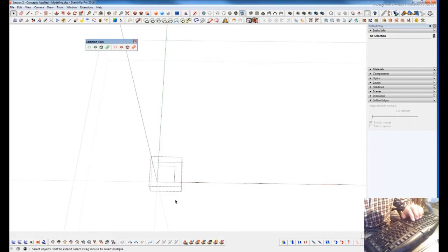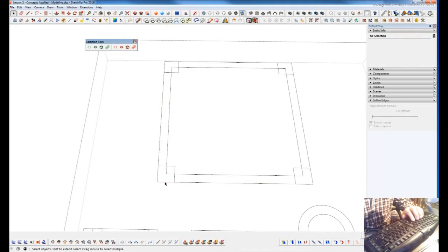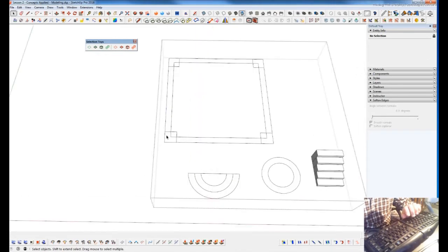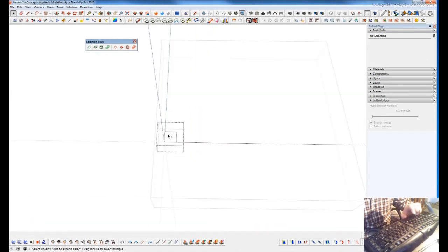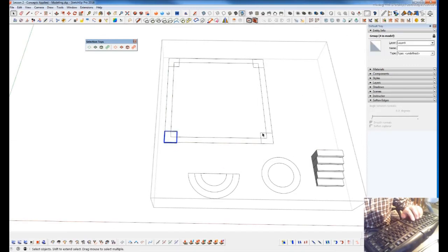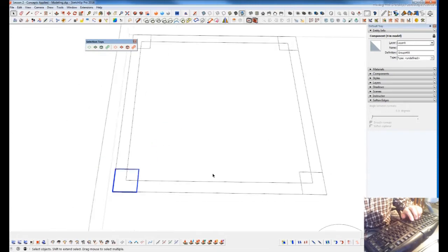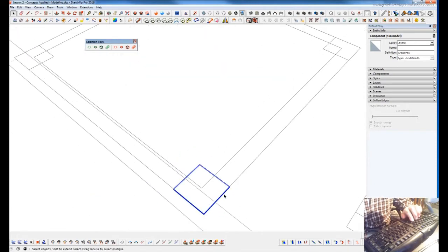Let me undo that, because I guess I got into edit mode, and it's assuming that I'm going to edit this, so now it's going to be different than the other ones in the model. So if I back it all the way out, undo it and get back in. Nope, gotta undo that. Now I'm back to 4 in the model. I can use my shortcut to convert this into a component, just Control G, and now I have 4 in the model.